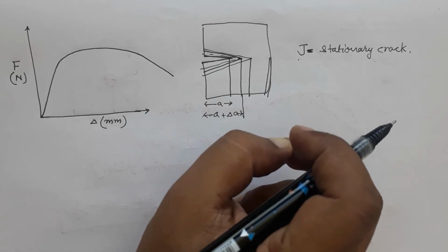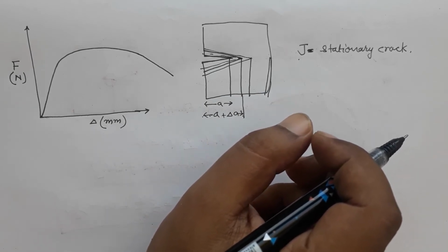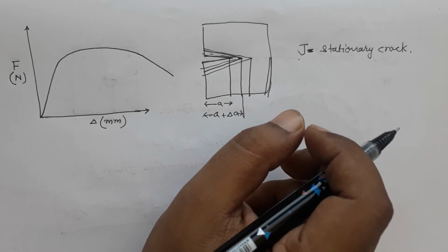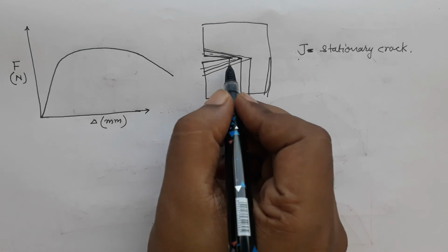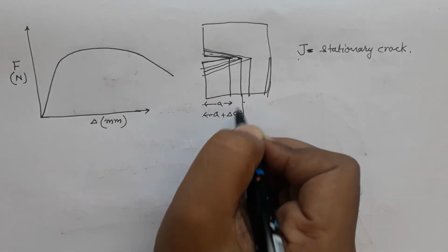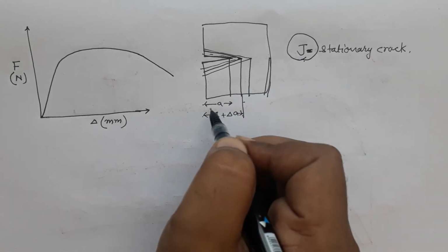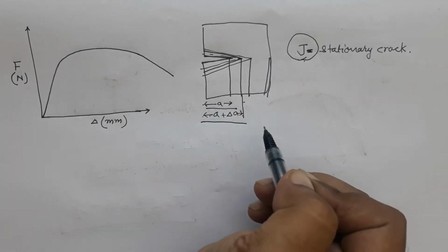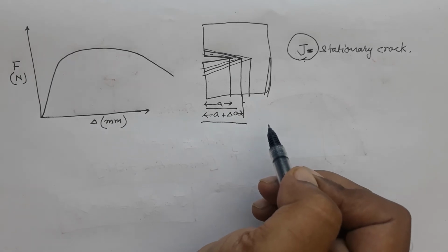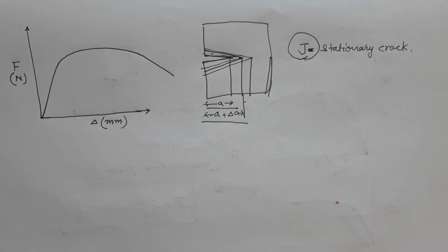So, we are not talking about microstructural defects. The singularity, the crack, we can call that also a defect. So, there are two different defects, because the geometry will be different if you have different crack lengths, and therefore, the value of J will also be different for these two cases. One case with a crack length of A, another with a crack length of A plus delta A, and J describes this difference in the energy.